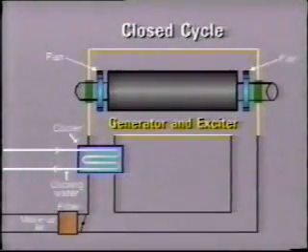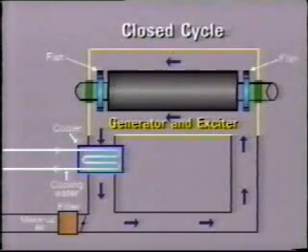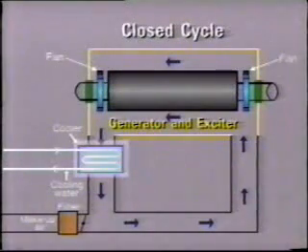Where the generator is located in a hostile environment, say very dirty conditions, the closed cycle air cooling system is usually employed. In this case, the same air is continuously circulated through the unit, and the air itself is cooled as it passes through a water-cooled heat exchanger.